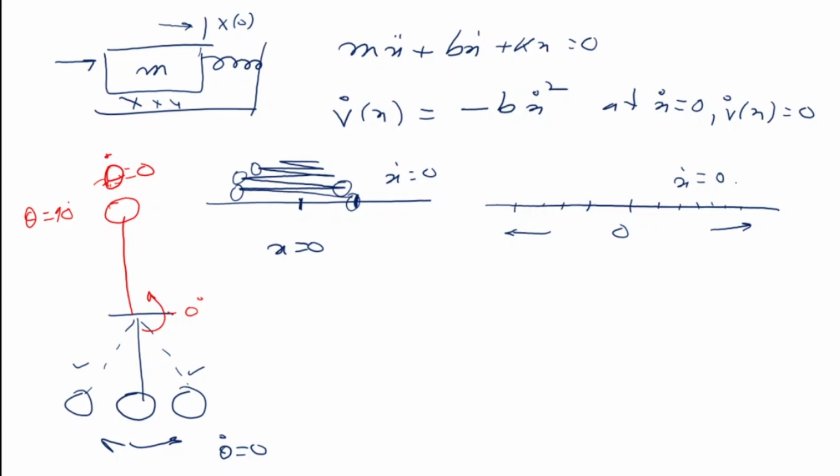Now if you look at this spring mass damper system, we have the mass which has moved here or it has moved here. At this end point, can the mass go there and sit there? Can it wait there? No, it cannot. It has to immediately go back. Why is that so? Because once you give it a small push and the mass has gone here, the spring is compressed. The moment the velocity becomes 0, the spring will push it back. So at those extreme points, the mass is subjected to an acceleration in the reverse direction.